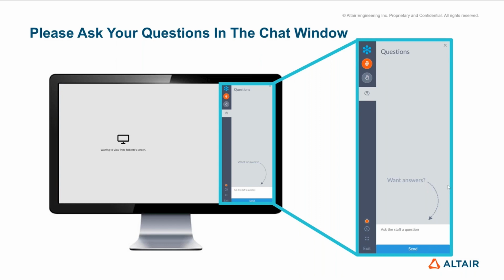You want the gate to have a lot of surface area, and you want to get that to solidify prior to the runner system. If you're not careful and you have a large fixture ingate, then obviously the casting becomes the feeder, and you have a lovely, nice sound runner system. So you've got to use what you've been taught or what you've experienced, but you want a lot of surface area so you can chill that gate off very, very quickly, so it doesn't influence the casting soundness.